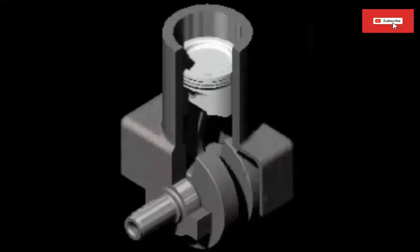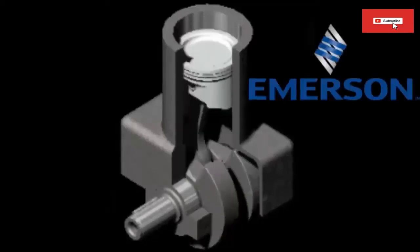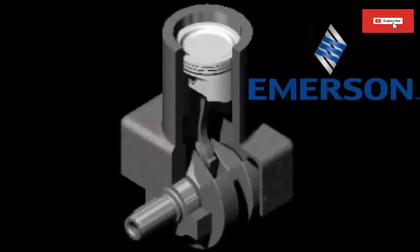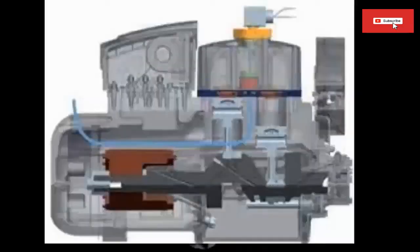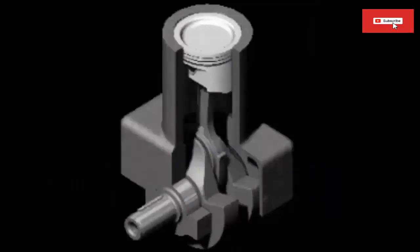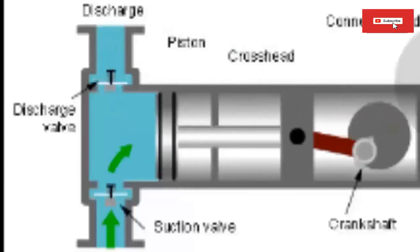For this reason, to improve the performance of piston compressors, their manufacturers have worked on perhaps the most influential factor in electricity consumption. We are referring to the control of the compressor's cooling capacity, or the way to only produce the cold that is needed, avoiding the on-off dimming method.